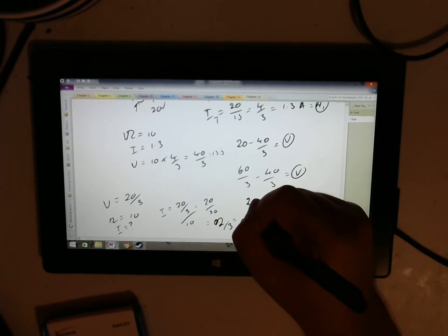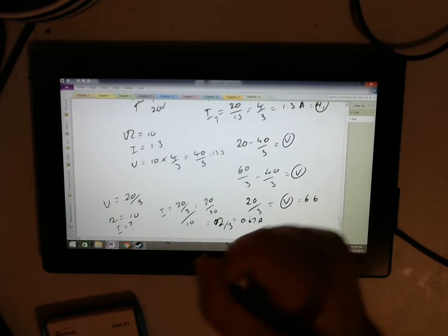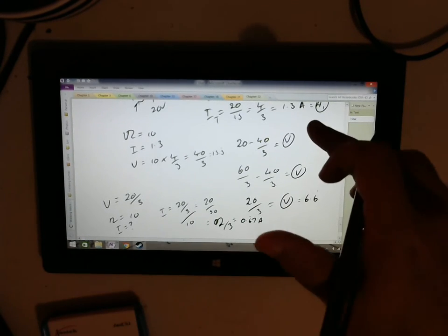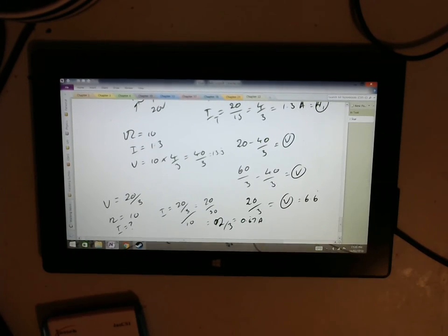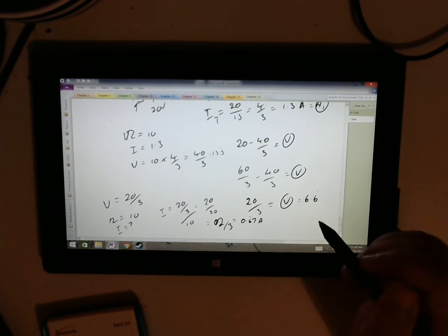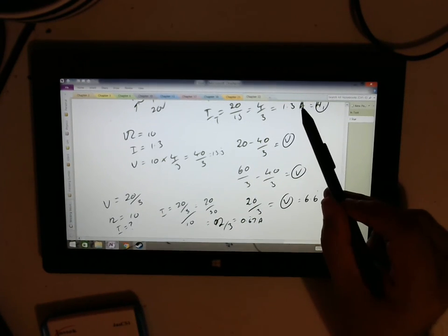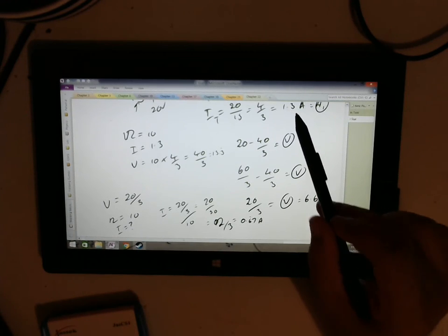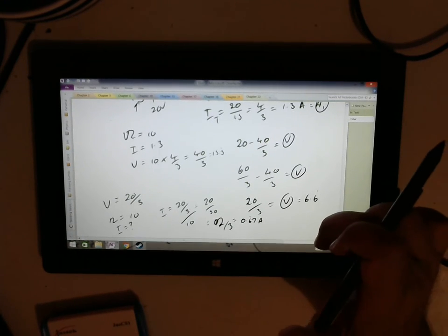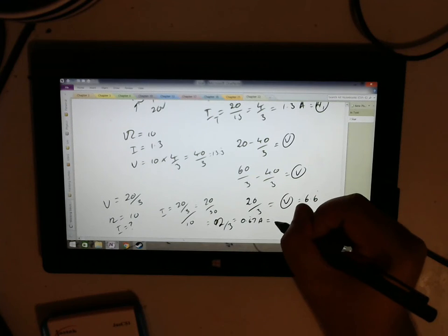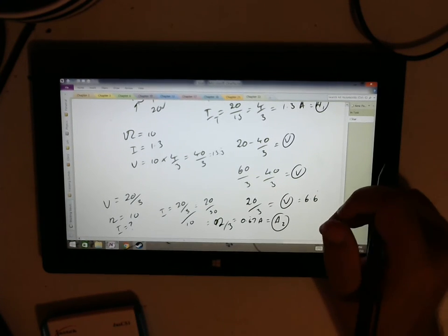or 0.67 amps. And if we look at this, that's 1.3, so 1.3 divided by 2 gives us pretty much close to that, because that's rounded off. That should be 1.3 recurring. 4 divided by 3 divided by 2 gives me 0.666666, 6 recurring. We can see then that that intuitive idea of just taking that and cutting it in half did match our answers, but we needed to show that it was going to be that answer, and that's for ammeter 2.